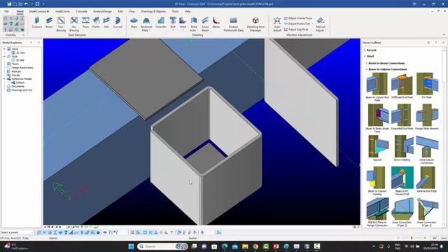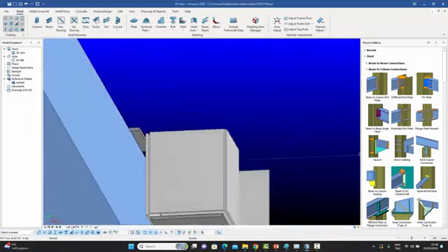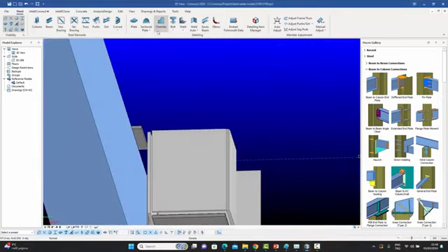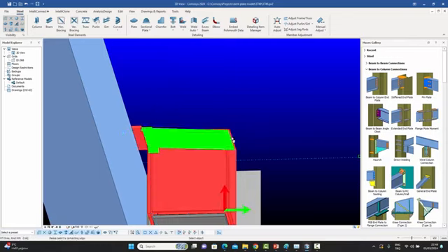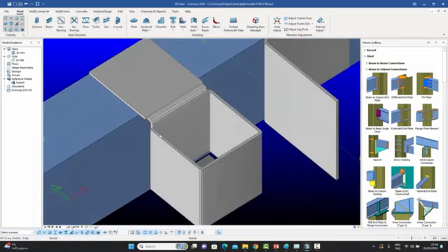Now, up till now, this could have been done with a normal folded plate as well. But now I'm going to connect this plate to this existing plate, and this will now make it a true bent plate. So let's look at it from here. Go to my cylindrical bent plate command, choose this one, the existing bent plate, and choose the new plate. And it gives me two options at this point. I want to choose this one, which is the direct connecting one. And you can see that it has now connected this folded piece to this new plate over there.